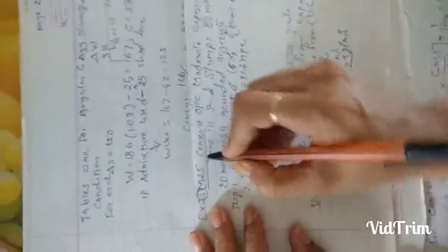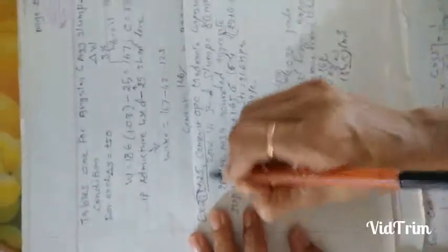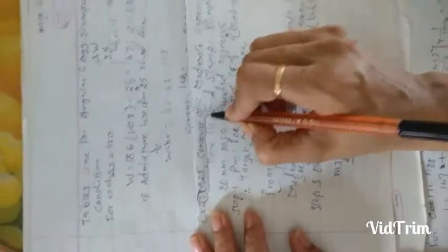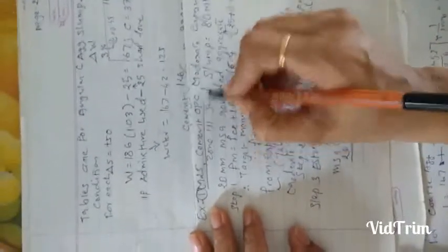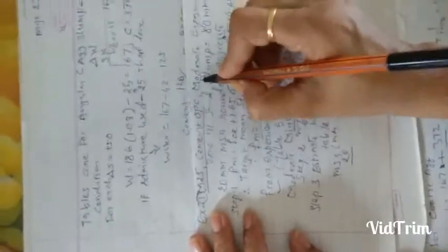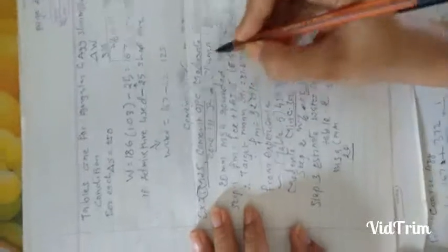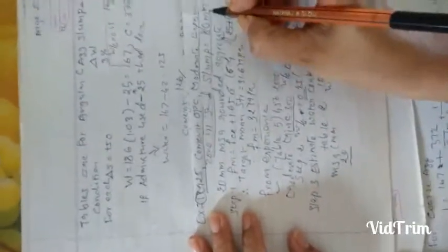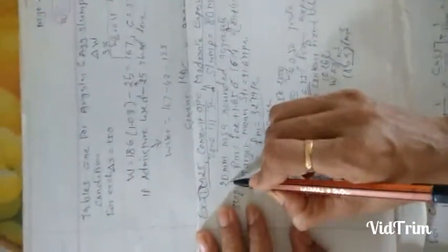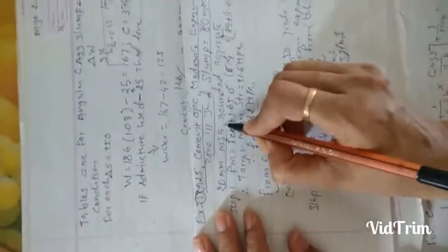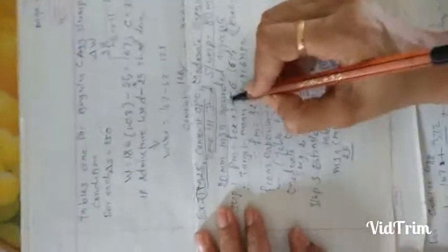So these are all design stipulations. First, M25 grade we considered, then cement considered is OPC, that is ordinary Portland cement, then exposure given is moderate exposure, zone 3 sand, and slump given is 80 mm and 20 mm MSA. Okay, maximum size of aggregate 20 mm, rounded aggregate.